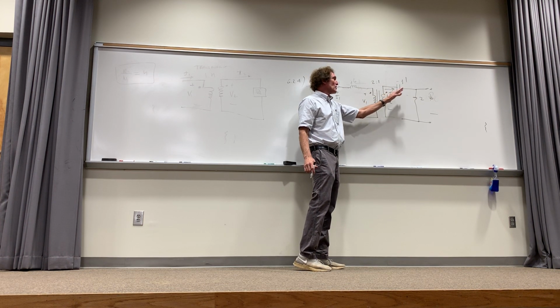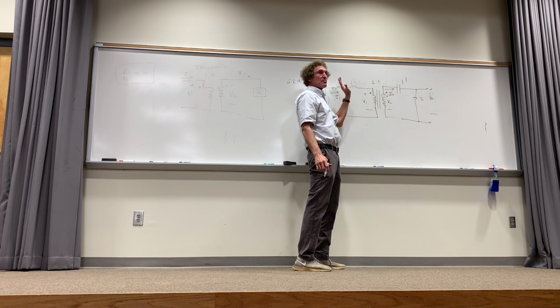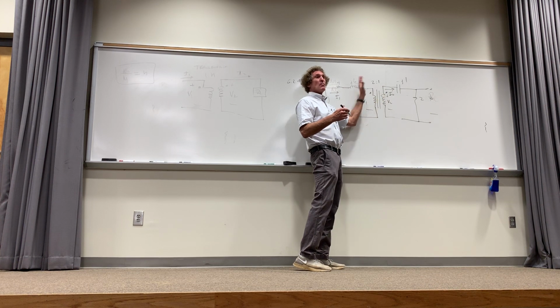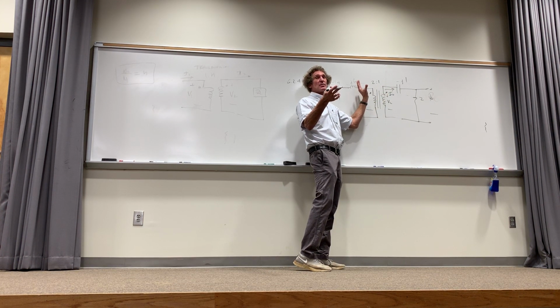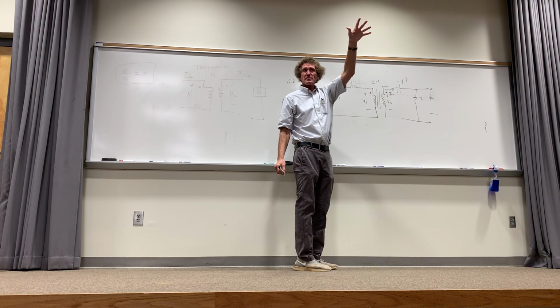On the actual secondary, class? 2 minus j1, right? When the impedance comes to the primary, it's going to be multiplied by the turns ratio squared, or multiplied by 2 squared. Do y'all see it? More turns here. When I reflect the load, it goes up by the turns squared. You follow me, class? Are you with me on this one?